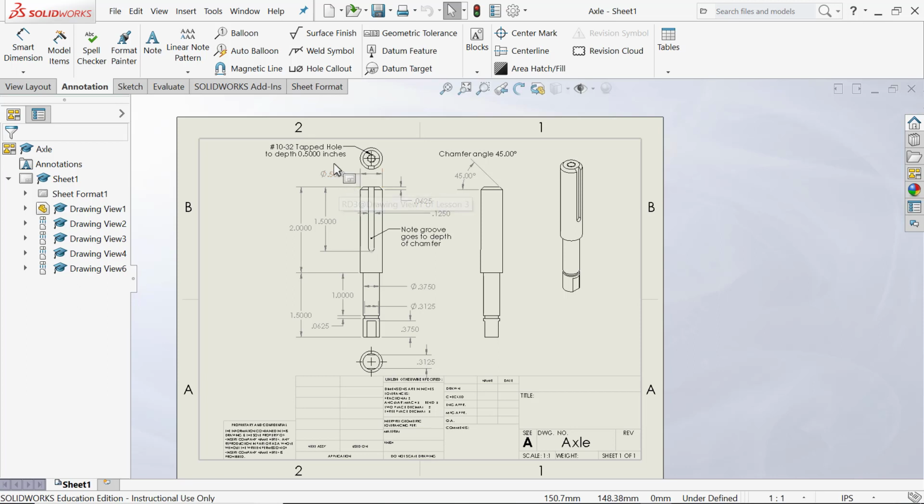And this time I'm spending here really is probably some of the most important time you have when you go to make a part. You think ahead: how am I going to create this part? What steps will I follow? Where will I locate things? What sequence will I do the features in? It's very worthwhile. So you'll create that and you'll extrude that 1.5 inches.